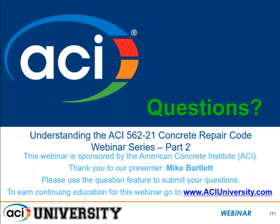Yeah, so that's a very good question. We'll start the answer by saying that the provisions in 562 and particularly the equation 6.4.3.1 that we showed in this presentation, those only pertain to cores that are 4 inches diameter or 6 inches diameter. If you have a 3-inch diameter core or a small core, then you're probably going to ACI 214.4R for assistance.